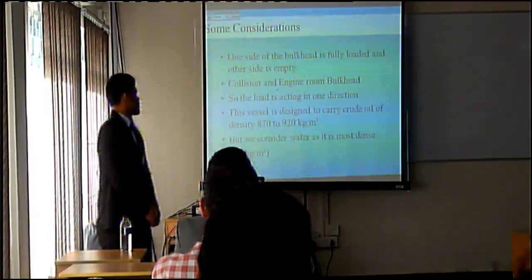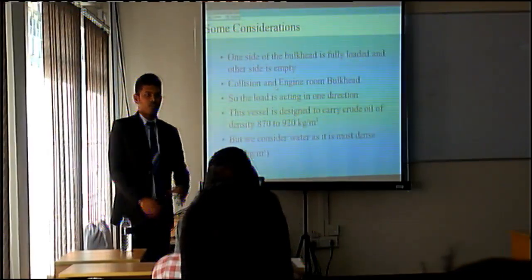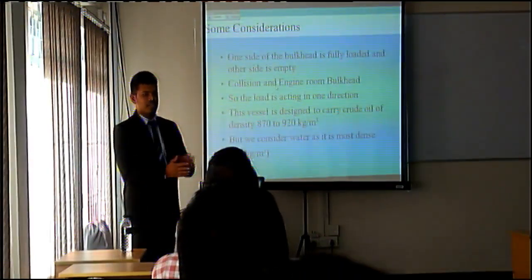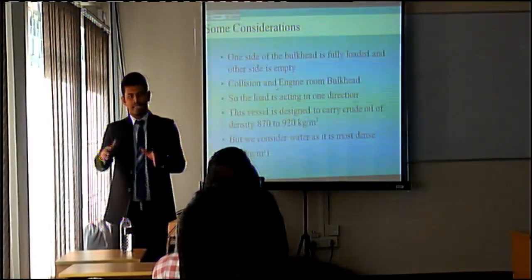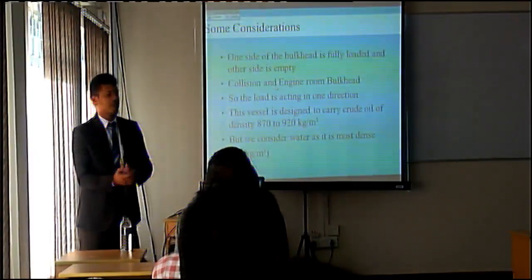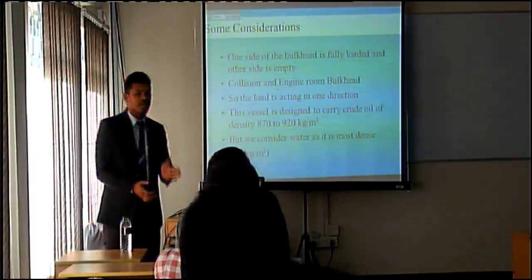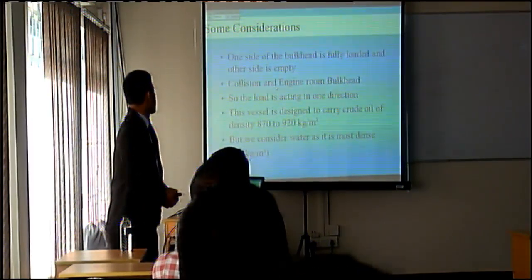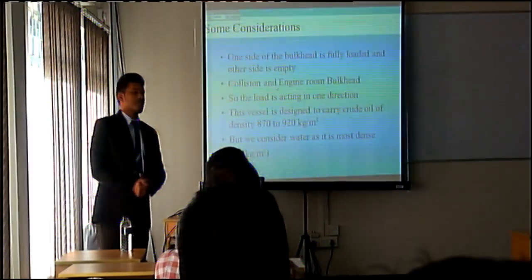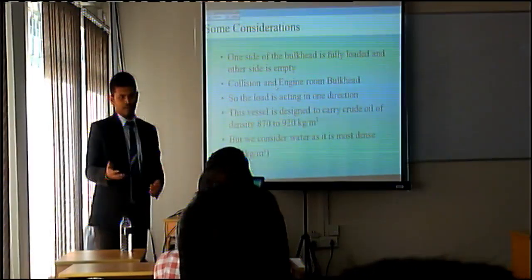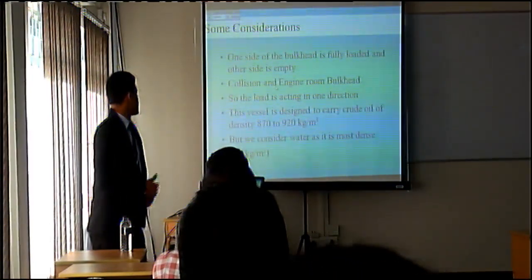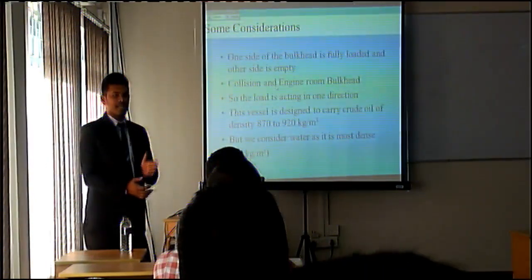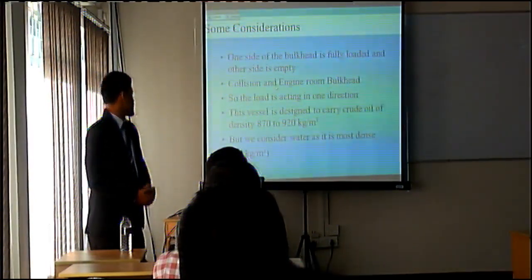Some other considerations: we are considering that one side of the bulkhead is fully loaded and the other tank is empty, because in this case the bulkhead will experience the most hydrostatic load. This type of loading generally happens for the collision bulkhead and also for the engine room bulkhead. So in this bulkhead, the load acting is in one direction.